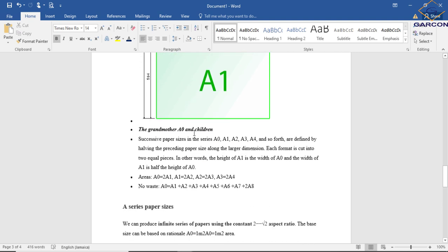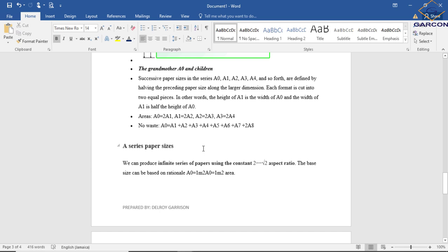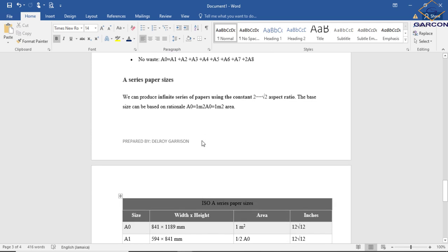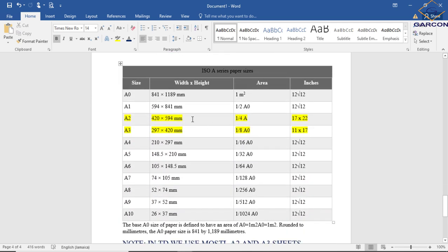So all of these notes will explain the different size papers, what they're used for and how you arrive at them. These are the two major sizes we use in technical drawing for high school. A2 is for fifth form, A3 is for fourth form. This is the measurement that you're going to use to draw your border. And then for the title block we'll use the standard measurement of 50 by 110 for each space that you're writing.